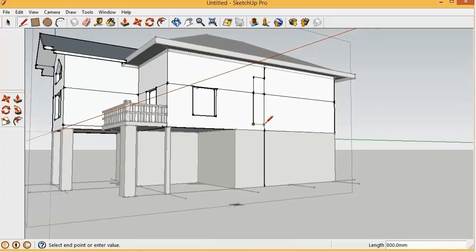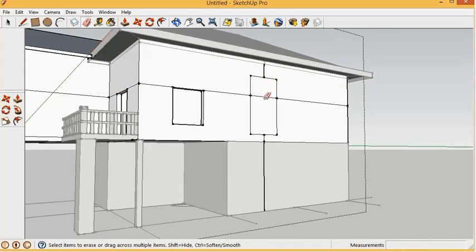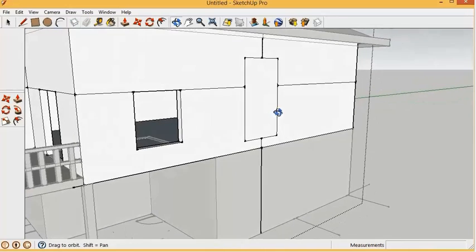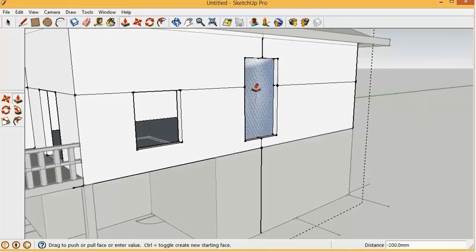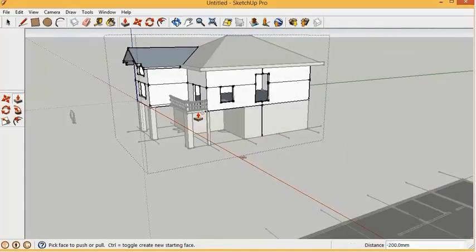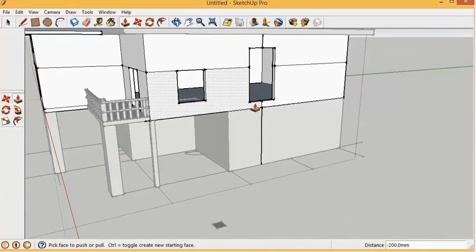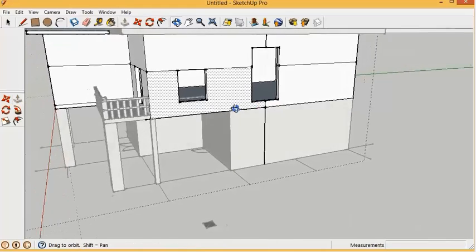And then we have the choice of whether to fill or extrude that text. I'm going to leave those off for now. And let's just go ahead and create just the basic text. So I'm going to select place. And now it creates some text. Now because I didn't fill it, it just creates the outlines of those objects.